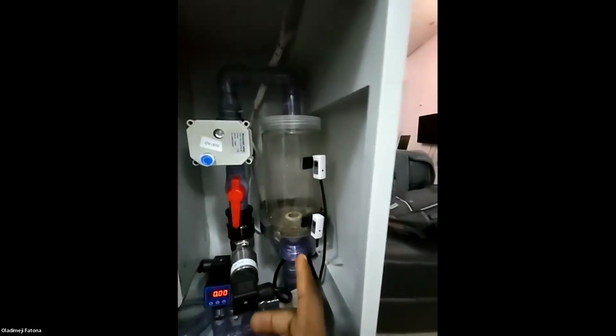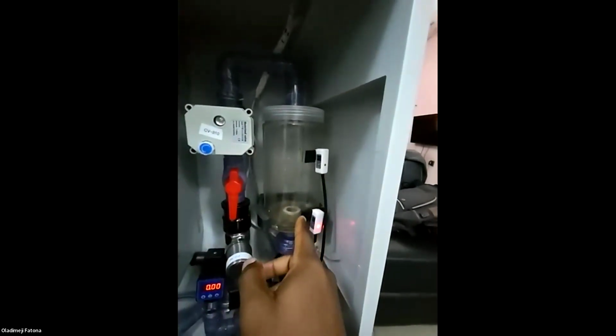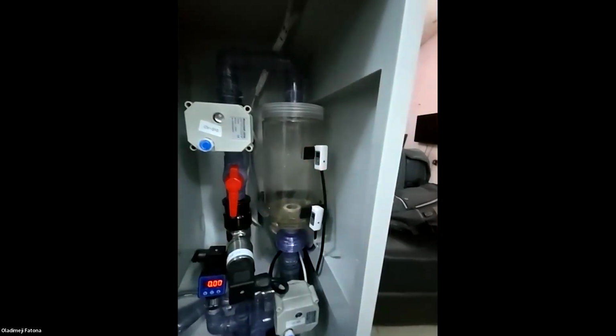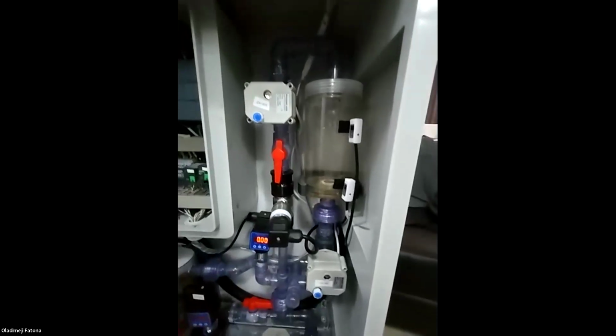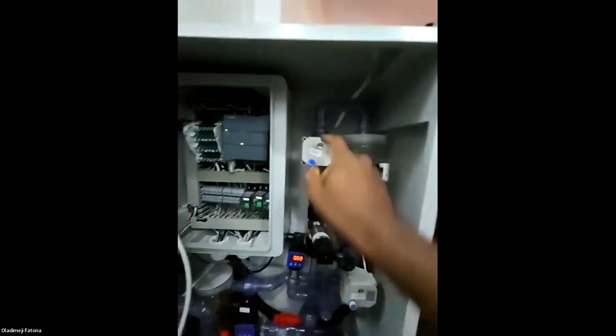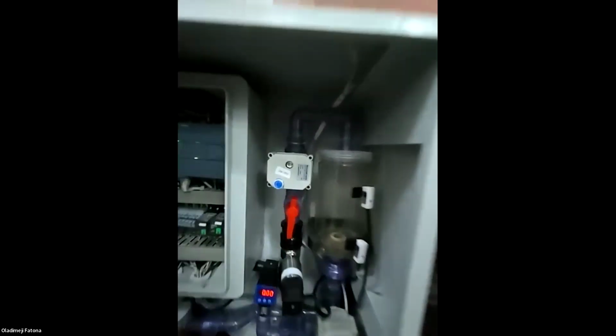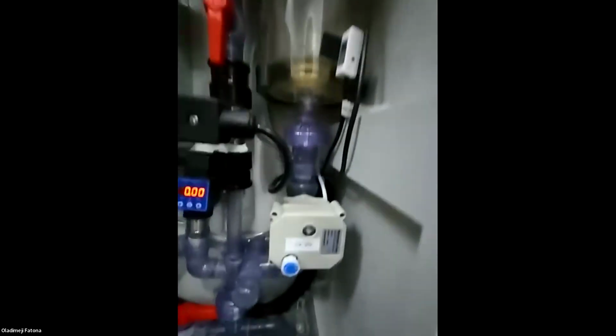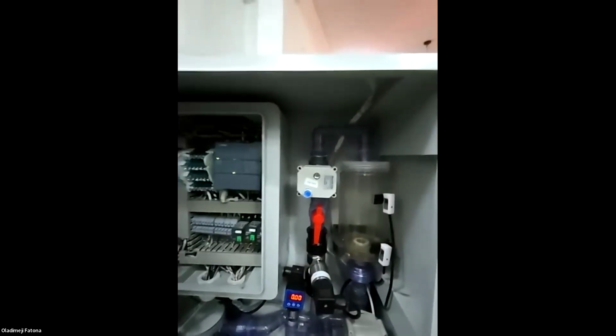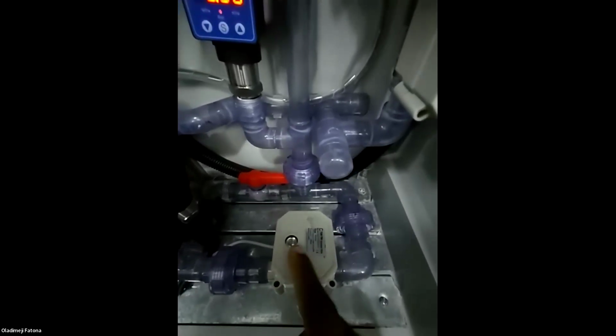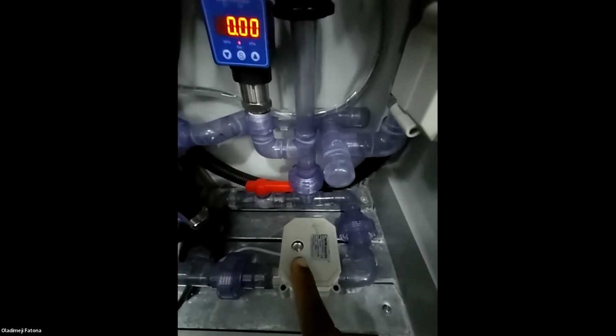Here you can see I have level transmitters, the level switches here. So basically they tell me, okay, this is for low level, this is for high level. Both of them are not active because it's below that. Then I have 2 valves here. These valves are digital outputs. They are digital valves. It means that they can either fully open or fully close. Then I also have an analog valve here. This analog valve opens in percentages, right?